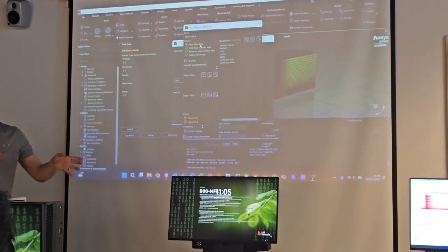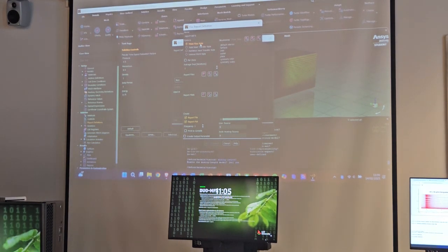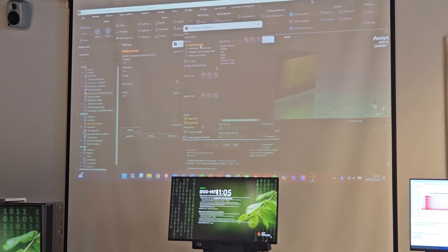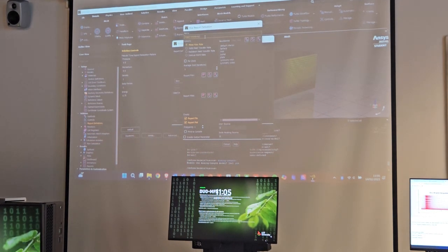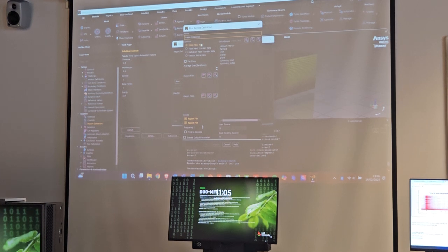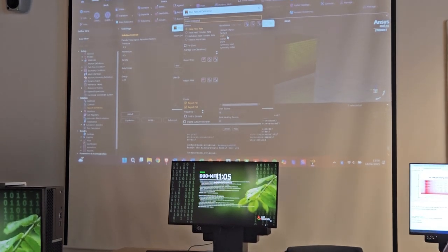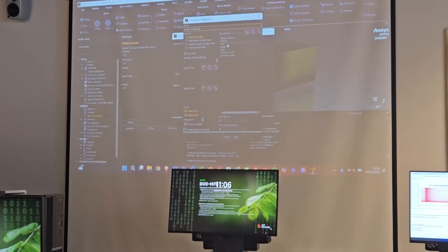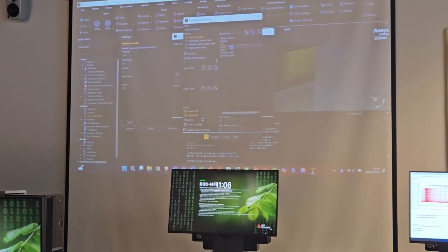If you don't have that condition, that means that your solution is wrong, because then you are breaking a physical law, that is the continuity equation. So we need to check that this is true, so we can create this report definition. I call it mass imbalance. And I can select the surfaces where there is fluid entering or exiting, so inlet and outlet.